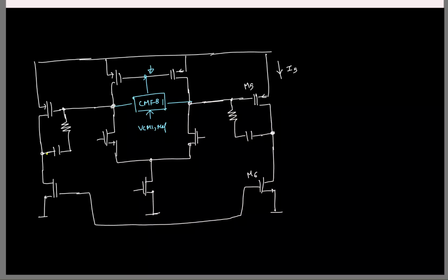Yeah. Basically, first of all, we can't use a MOS-based common mode detector because this is going to have maximum swings. The only option we have is to use a resistor, but the resistor could load and reduce the gain. But if you remember, this was already designed such that it can drive a load resistor. So you can easily choose my common mode resistor RCM to be large enough compared to my load and get away with it. Whereas it might not be easy to do that for the first stage because here I've used a normal first stage. I could use a cascode here also for the first stage, right, to have a very large gain.